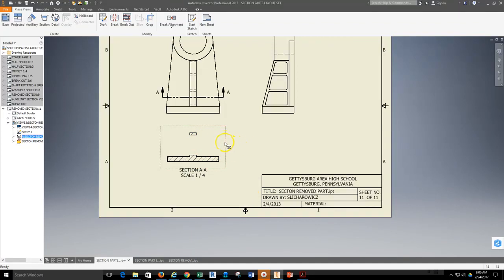By doing this, I can now move this particular view around my drawing. And this is why this section view style is called a removed section, because you're removing it from the relationship of the view. Every other section that we've done up until now is set up directly in line with what would be the multi-view projection. By removing this particular section from its position, we can now place this somewhere else on the page. We can also rotate and align these sections with subsequent section views.